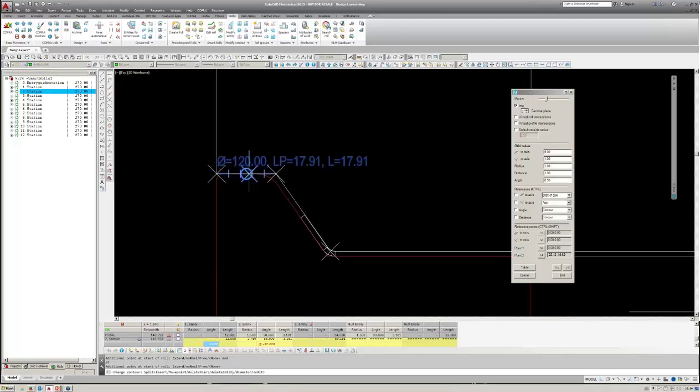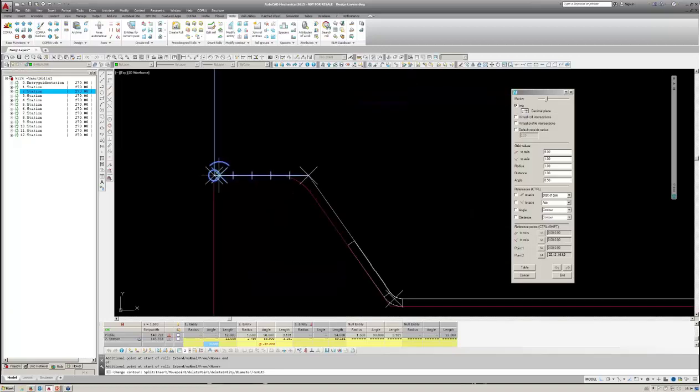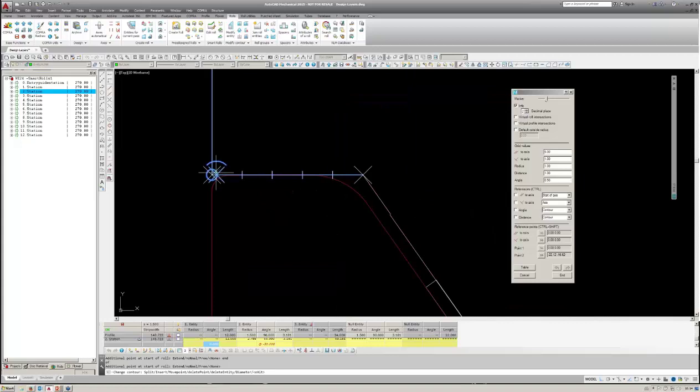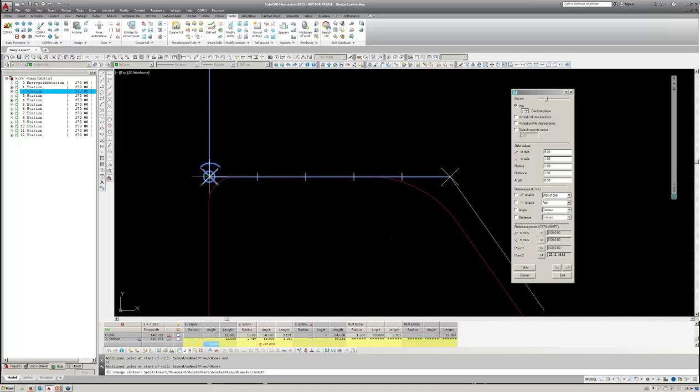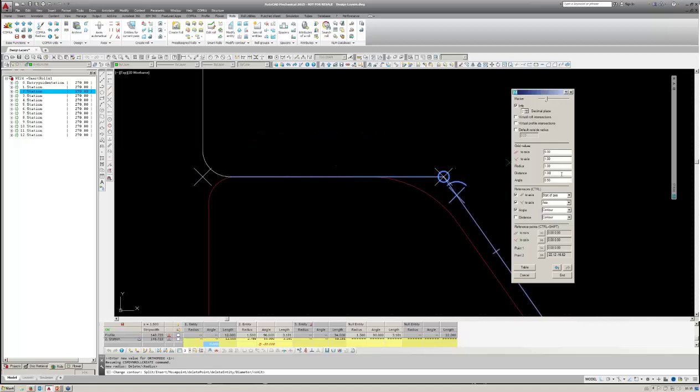Now here, I'll add the radius first, just so you can see some of the possibilities. So here, I'll zoom in a little bit more. Pick the radius, hold down Control and Shift, and there's the 2mm radius. My flanges are still meeting, so now I'm going to change it. You see my material thickness is 1.5, so I'm going to make the setting gap here 1.5.